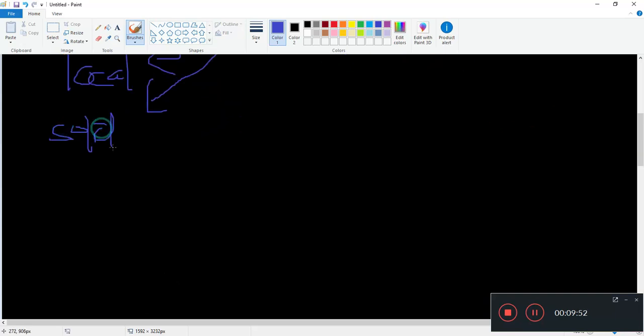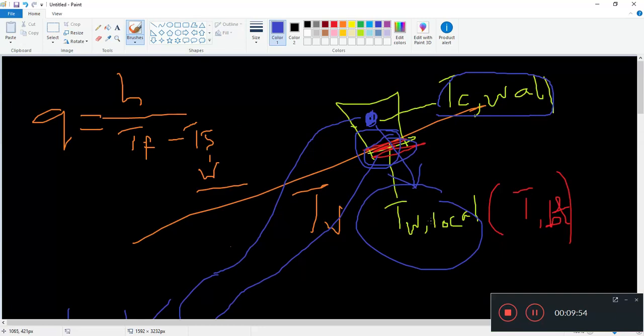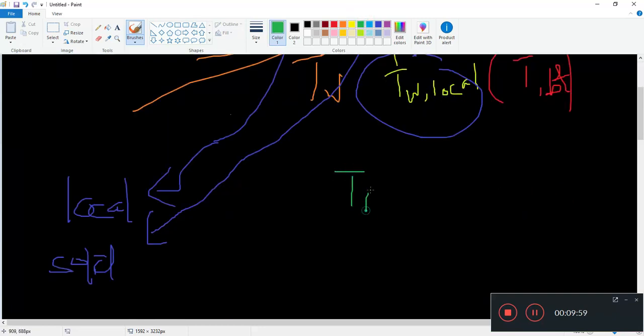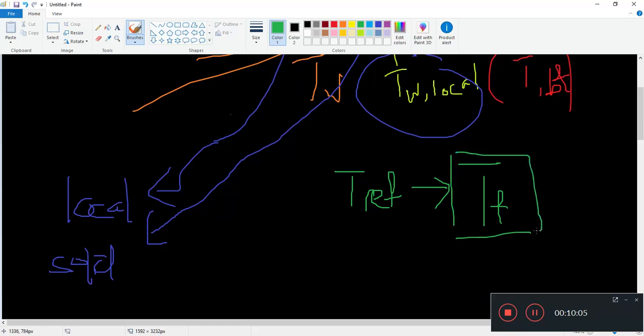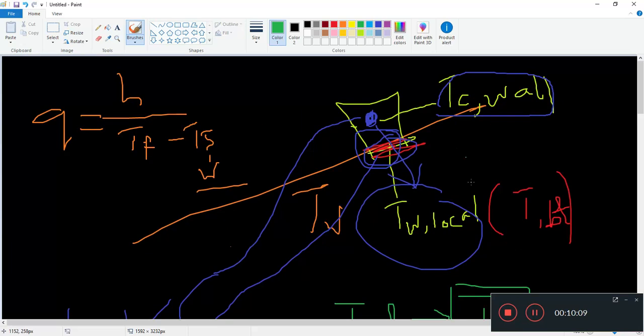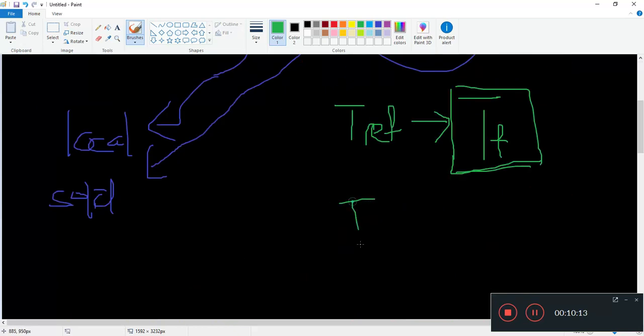Now, if we were to use a reference temperature model, if you use a TREF, that's whatever you key in, and that will usually be the fluid temperature, some reference fluid temperature, and we'll have this local solid temperature being used here. So this will be T solid.